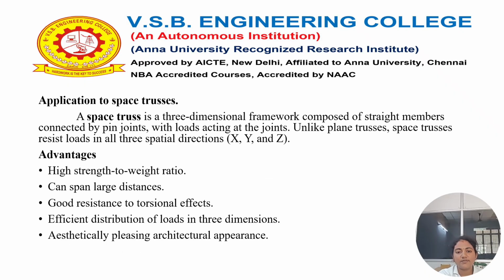And the application of space trusses. A space truss is a three-dimensional framework composed of straight members connected with pin joints, with the load acting at the joints. It is mainly used in industrial areas where there are large spans and we can't use concrete structures.